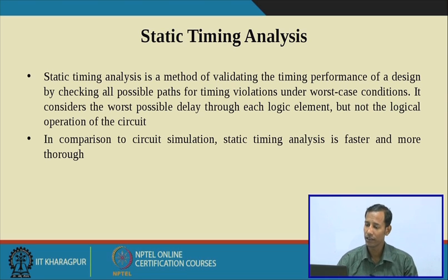Static timing analysis is a method of validating the timing performance of a design by checking all possible paths for timing violations under worst case conditions. It considers the worst possible delay through each logical element, but not the logical operation of the circuit.